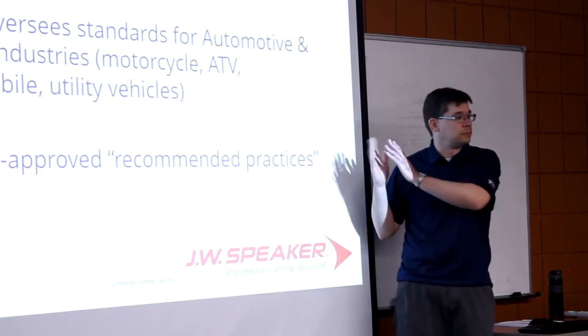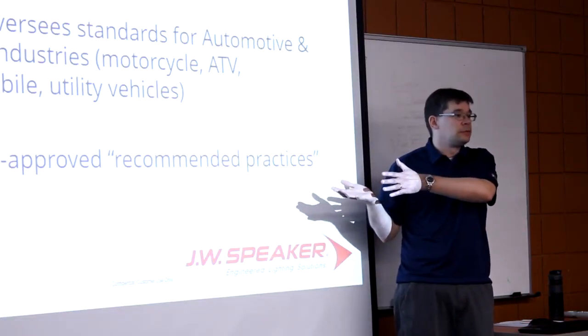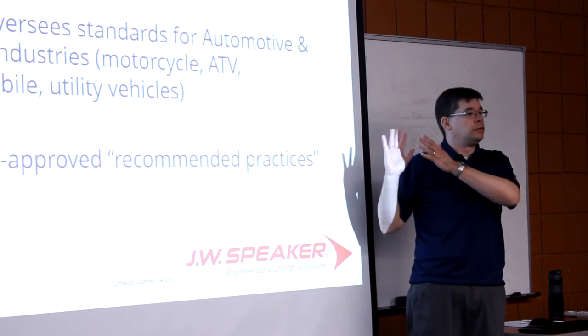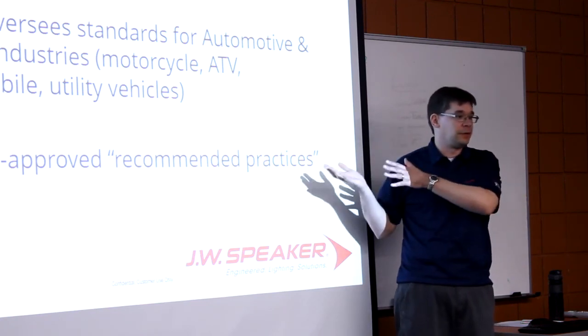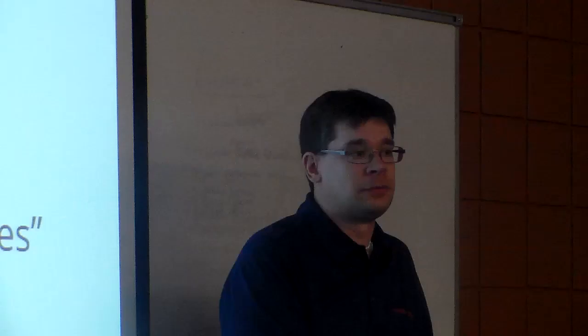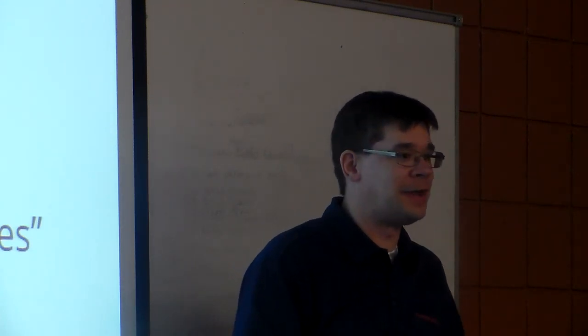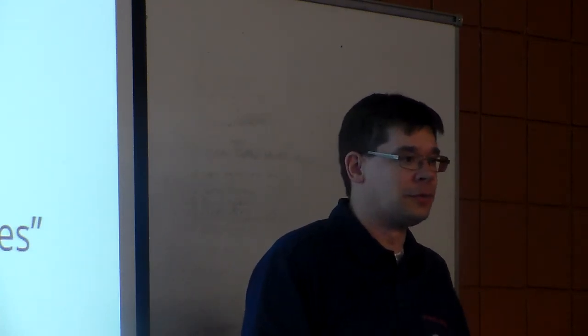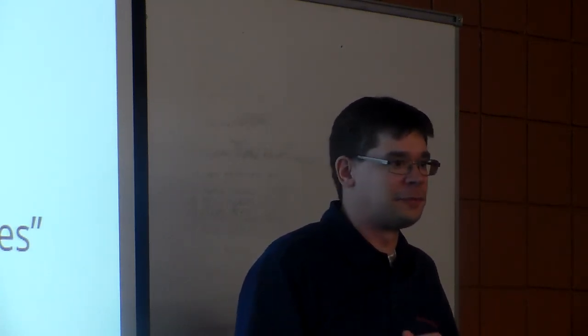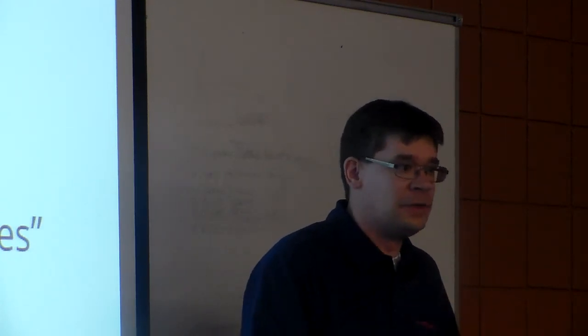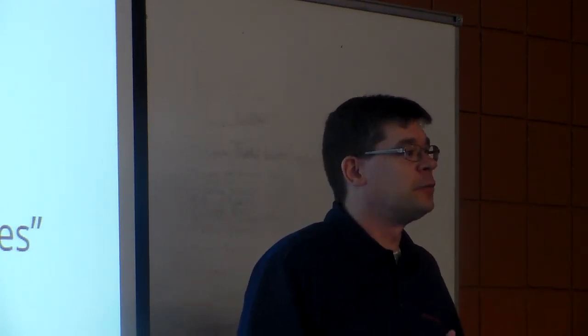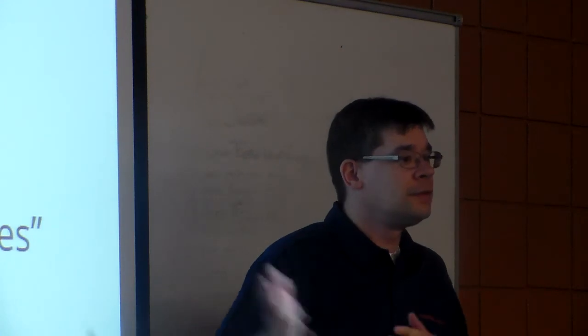FMVSS 108, the law, is really based off of SAE standards. The issue is it was based off of SAE standards from a long time ago, because like I said, the law does not change very often. The words LED aren't in FMVSS 108 anywhere because they don't update it, and there are some issues we have to deal with because of that.